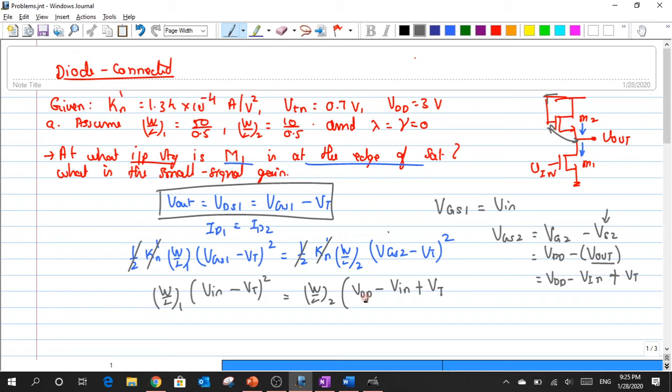And apart from this entire expression taken as VGS2, we also have one more Vt that is sitting over there, which has to be added along with this expression. So now you could see that we could further cancel out these Vt's that are coming out of VGS2 and the VOV2, right?